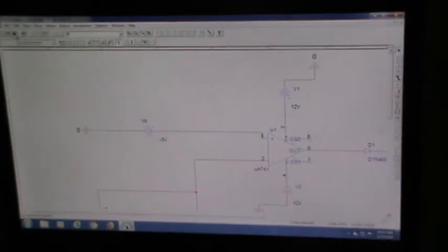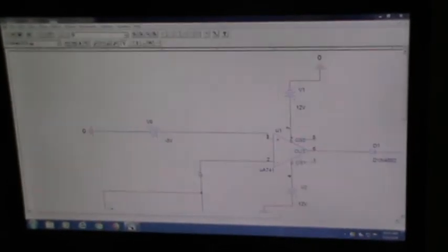Let us check. Go for save. Again, PSpice new simulation window. There you can give any name. Okay, create it. One of the windows will appear down, it will be blinking. Just go for it. Then here what you have to select is time domain transient, and run to time is 100 milli, and step size is 0.01 milli. Okay, then apply.